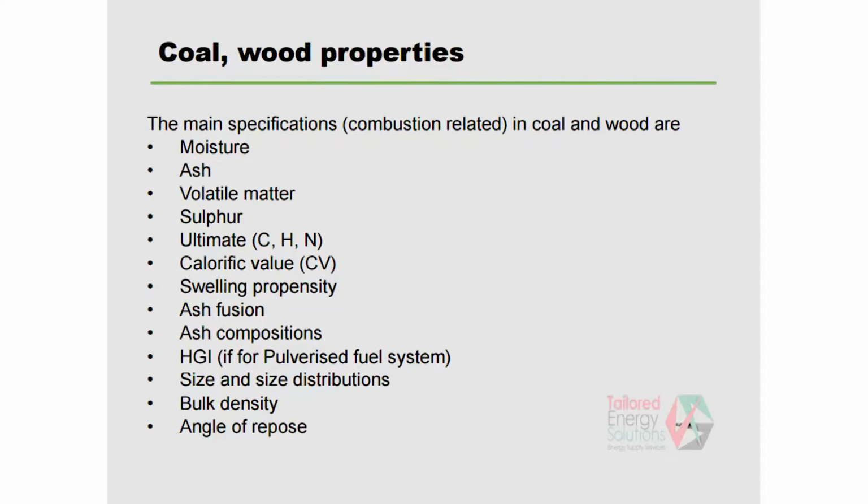Okay. For the ash, the residual stuff, when you talk about the ash content, we always want to talk about what is the condition you tested. For coal, ASTM standard 815 degrees for more than 2 hours. For wood, ISO standard 600 degrees. That's quite different conditions. Because the ash content is the yield right at that condition, we need to specify the condition very, very carefully.